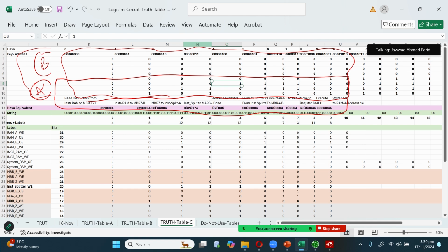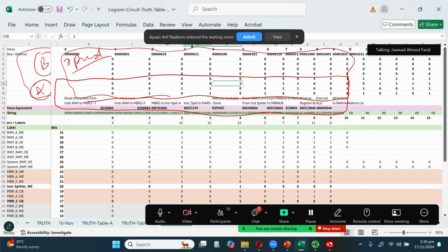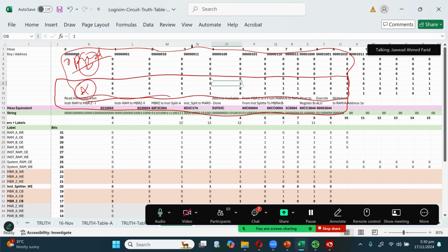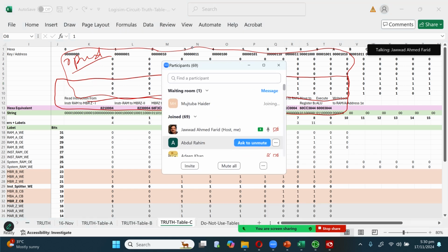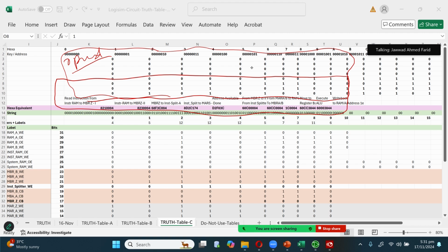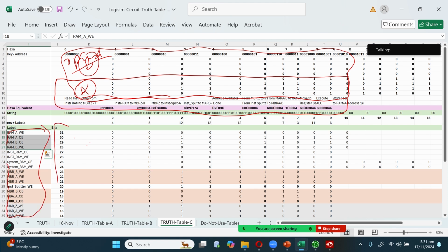The second part of this addressing scheme is the opcode. And right now that opcode is 4 bits, but don't worry about that. You can easily switch it to 5 bits later on. That's not an issue. For now, I think what we're trying to do, we're trying to get a sense of, once we get the addressing scheme right, what happens next. So if I have the addressing scheme right, then from my perspective, what I then need to figure out is that all of these signals that I've identified mapped to these specific bits, these are the desired values that need to be generated.